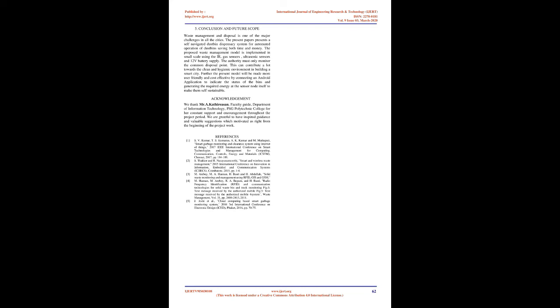3. Flow diagram. 4. Results and discussion. All the hardware modules are implemented in real-life dustbins as shown in Fig 4.1. It demonstrates the working of IR sensors to detect the presence of a person, which gives the signal to the DC motor to open the lid of the dustbin. Therefore, the automatic opening and closing of the lid helps the person to throw the garbage inside the dustbin. This will help to reduce the spreading of diseases. An Android application monitors and maintains the dustbin. Output data: a normal pictorial map is used to detect the dustbin.